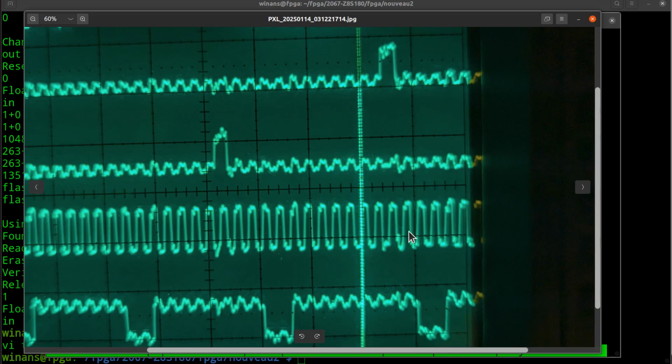Optimally, this would be done over here on the falling edge of T3, except if I wanted to use this same decoder, like I said, during memory transactions, they don't have as many cycles, and I have to do it on the 3rd clock instead of the 4th one in the total sequence of the machine time states.